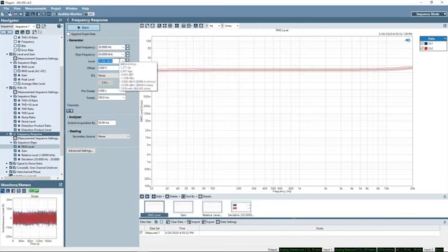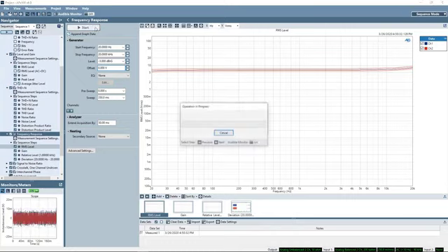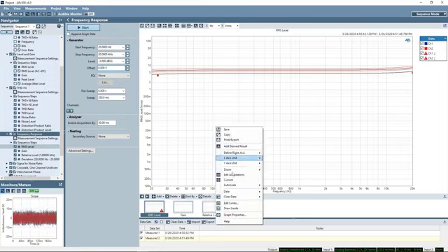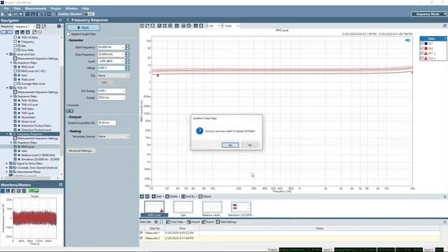If I change the generator level to -3 dB, I can show you how the limit failure looks. I'll enable Append Graph Data so we can see two data sets at once. You can see the fail indicators here and below in the film strip. I'll leave the generator at -3 dB so this result fails when we run the test sequence, and we'll see the fail indicator in the navigator and on the report as well.